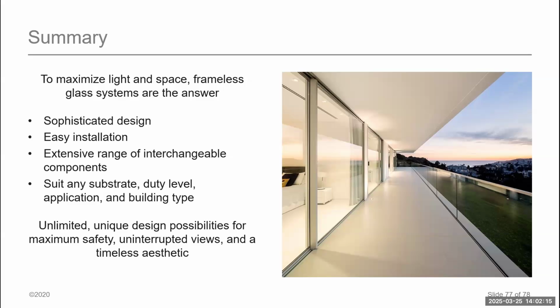The other thing that I would like to say, and is something that people may not realize in the market, is that base shoes are actually the system component that will best meet an overall hurricane type environment than using a post and rail. And the reason why is when you get into a post and rail situation, you're getting a transfer load where you're transferring anywhere up to 10 to 12 kips of load onto the post itself.